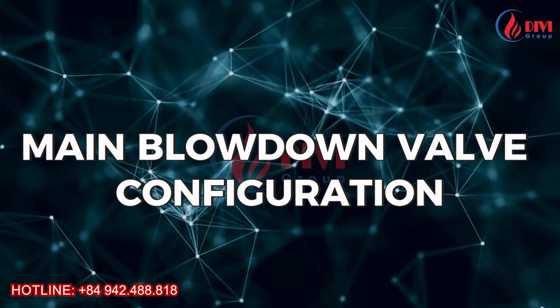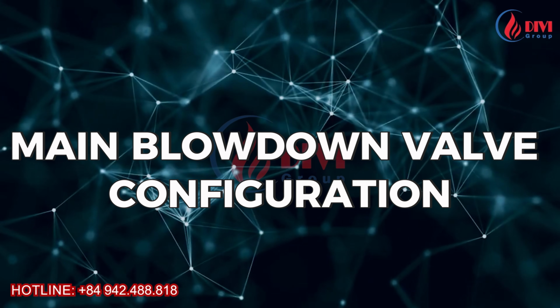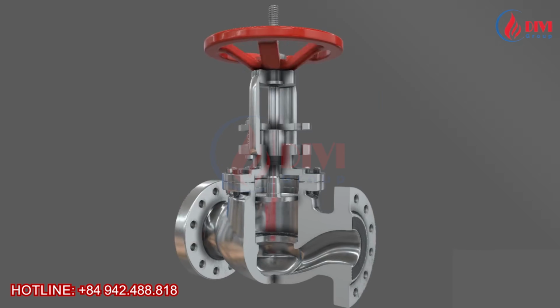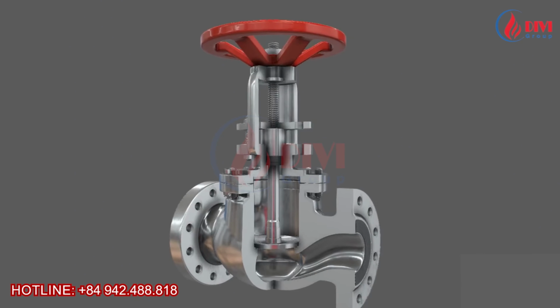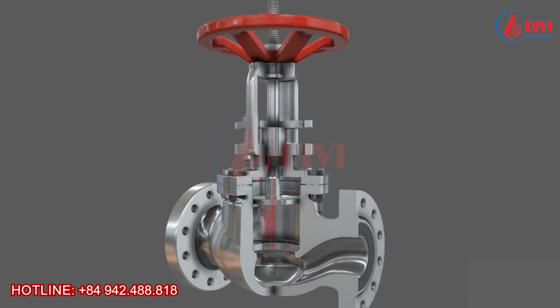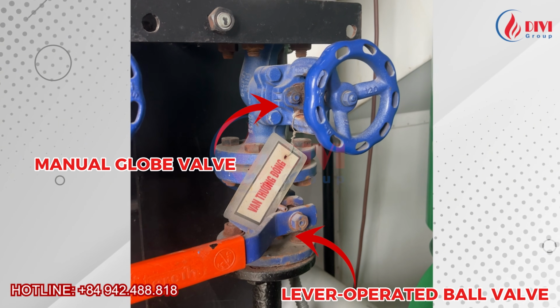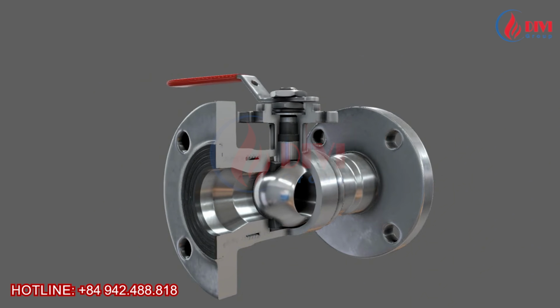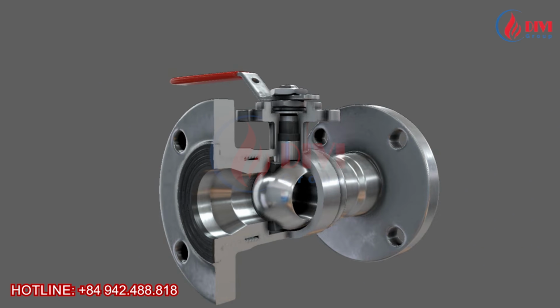Main blowdown valve configuration. For main blowdown lines such as the boiler shell and furnace, it is mandatory to install two valves in series. First, a manual globe valve, installed close to the boiler. Its function is to isolate pressure and protect the downstream valve. Second, a ball valve or quick-opening blowdown valve, used for rapid discharge, which should not be installed too close to the boiler, as scale buildup can cause leakage.